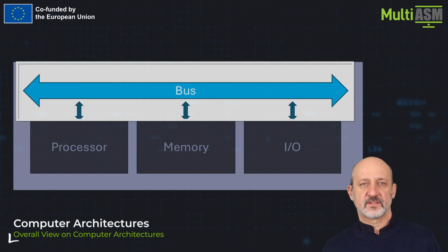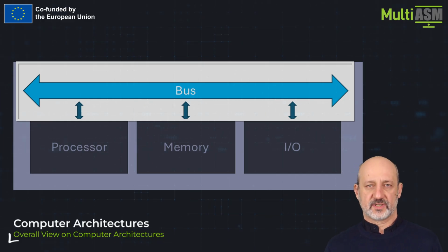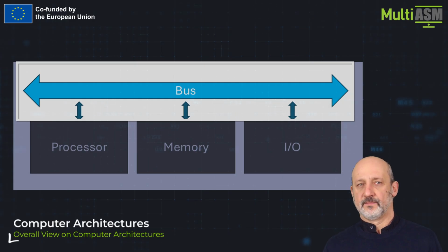The data bus is used to exchange data between the processor and the memory or peripherals. The processor can read the data from memory or from peripherals, or write the data to these units, previously sending their address with the address bus. As data can be read or written, the data bus is bidirectional. The number of bits of the data bus usually corresponds to the class of the processor. It means that an 8-bit class processor has 8 lines of the data bus.